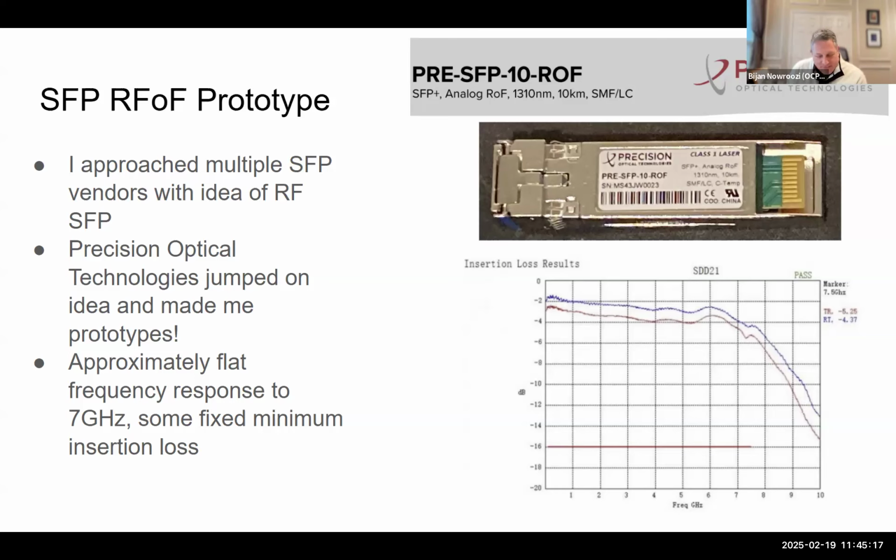I was just thinking about diversity and putting two antennas on the same fiber. Yeah, I mean, no reason you couldn't, right? If the antennas are not correlated, then the way it was explained, there should be isolation, there shouldn't be an issue.